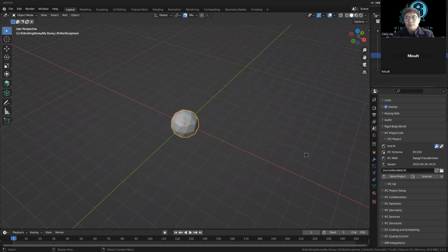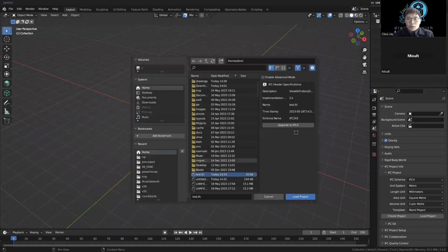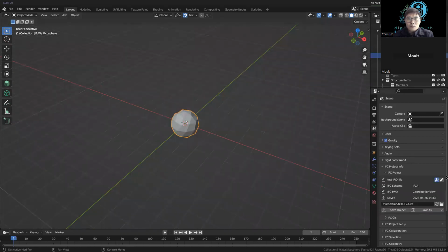Right, so that's done. And you could upgrade this to IFC4. So for example, if I went in my test, I can press this button, and there we go. We now have an IFC4 version of it, and there you have it. It's now IFC4. Now, I would hesitate slightly before encouraging anyone to downgrade. It is technically possible, but there are a few maturity issues with it, and also there's very few reasons why you'd actually want to do so in the first place.